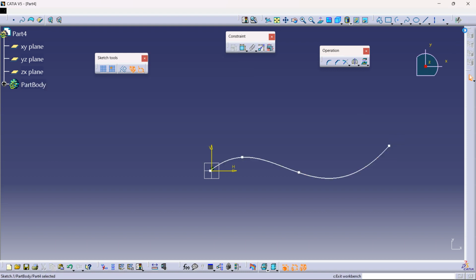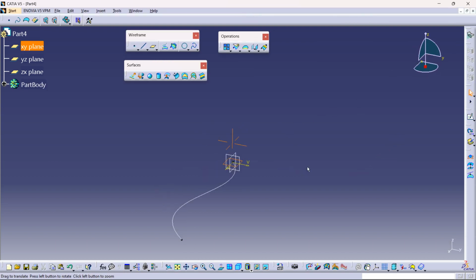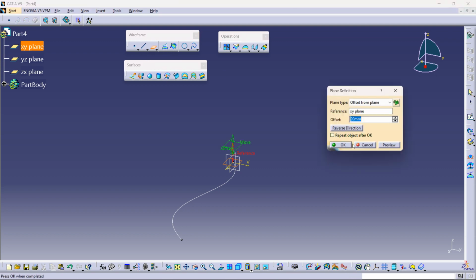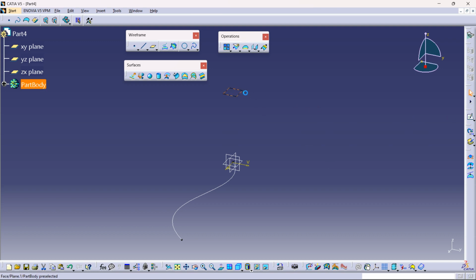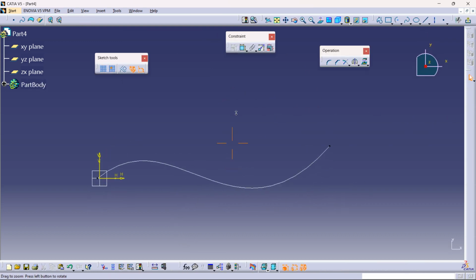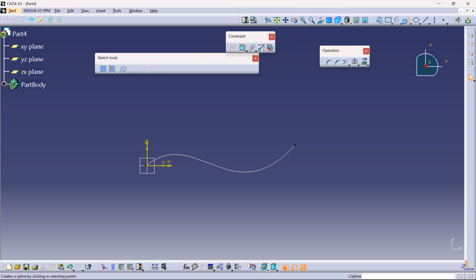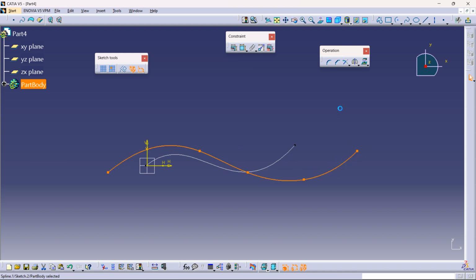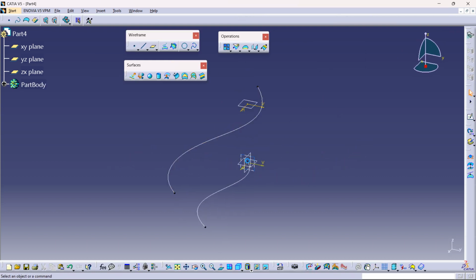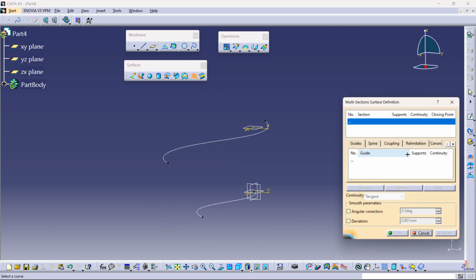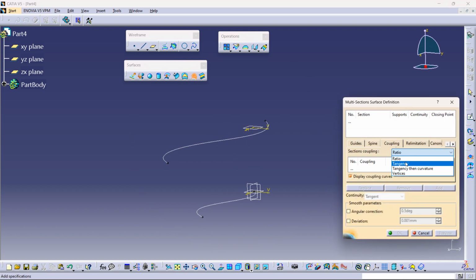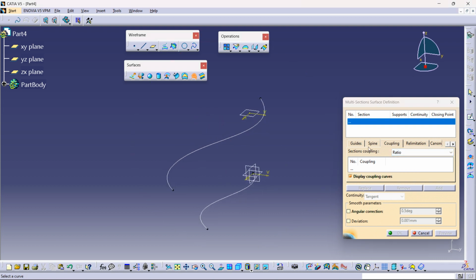For that, what we need is two curves, two different geometry. The number of vertices has to be matched. Otherwise, we know there will be some problems, and also I think we know how to solve those problems. Vertices option and all under multi-section. Remember this option, vertices. If the number of vertices are not matching.